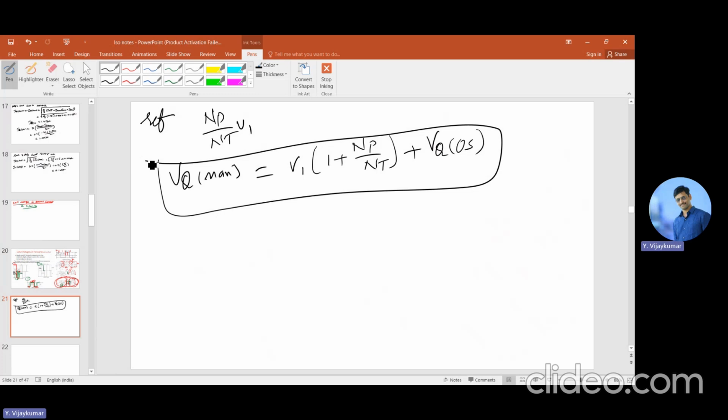It also requires a derated semiconductor device. You know that a semiconductor device has a voltage withstanding capability. If we manufacture for the same amount of voltage that we are going to operate at, it cannot withstand it. So we must have some safety margin on the operating voltage.